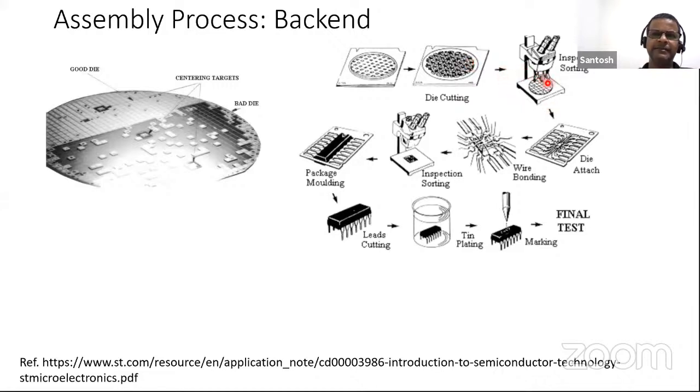And then these individual dies are picked up and go for different types of packaging. So what you see here is basically a lead frame. Just now it was described by Mr. Sahu that this is a lead frame based package, which is basically this called DIP. Finally it goes for final test, and then it goes for marking.